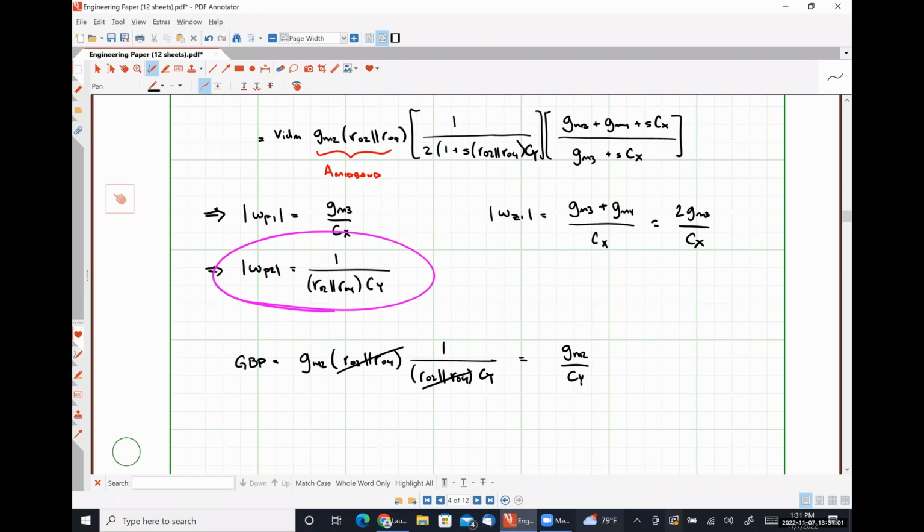Or another way to think about frequency compensation is what happens if we include feedback? Because as we all know, op amps, generally speaking, are not operated in an open loop configuration, but instead, for amplification purposes, are usually in a negative feedback configuration. So we are going to see how, with a capacitive load, a simple unity gain buffer makes this device unstable at present. So that's what we're going to talk about on Wednesday. All right, I'm done.